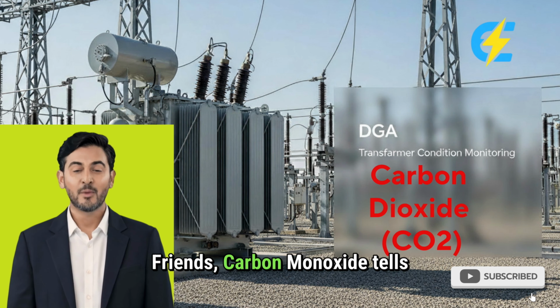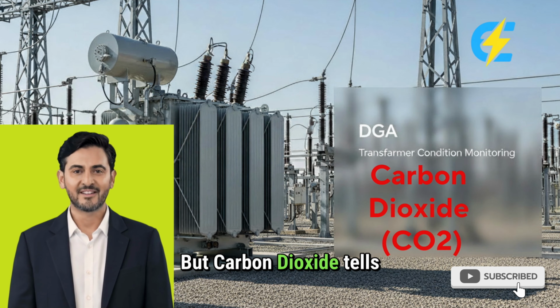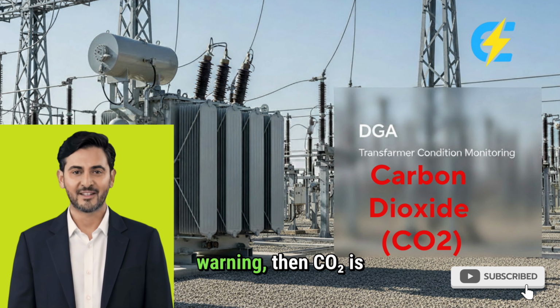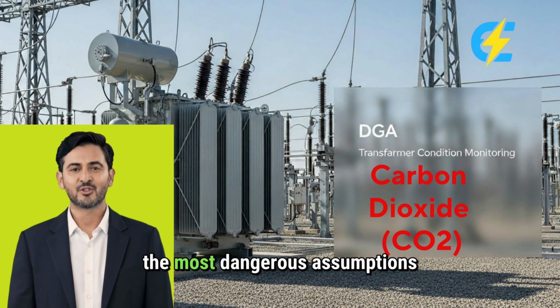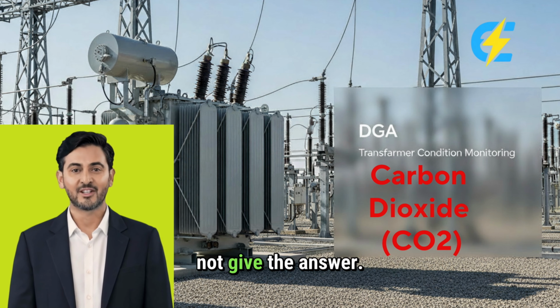Friends, carbon monoxide tells you that paper is degrading, but carbon dioxide tells you how far that degradation has gone. If CO is the warning, then CO2 is the history. Most engineers look at CO2 values and say, it's high, but normal. That is one of the most dangerous assumptions in transformer diagnostics, because CO2 alone does not give the answer.